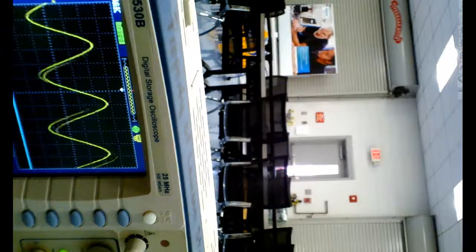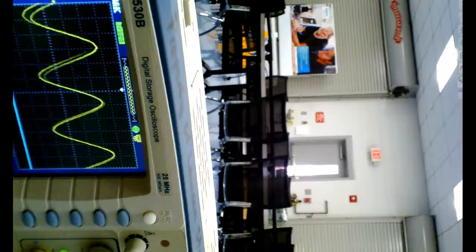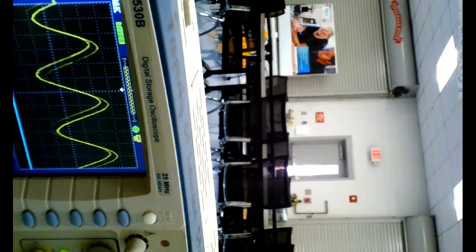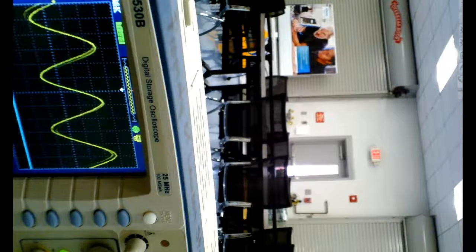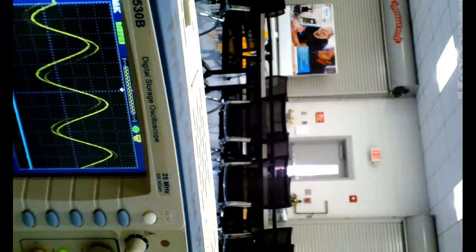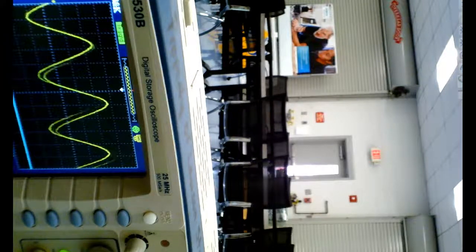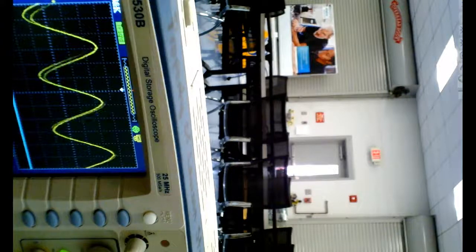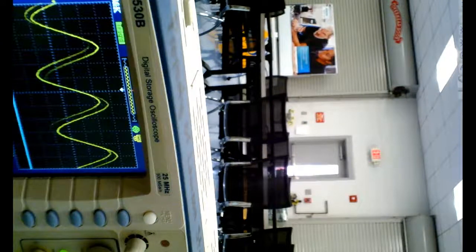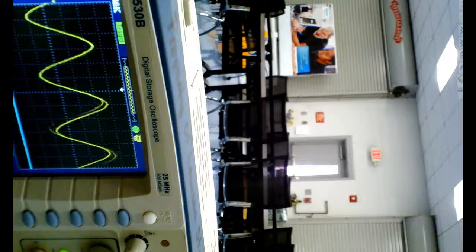All we have to do is come up with some type of electronic circuit that can detect that change of opposition. Here we don't teach those electronics, but believe me, we have what we call comparators, that can literally compare a set point to a back point, and if they don't compare out, it triggers a change. And those circuits are not really complicated.